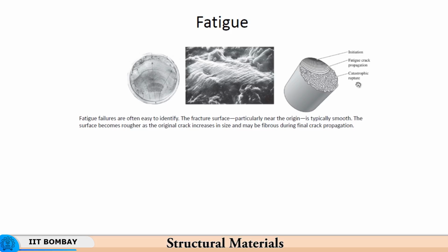Whereas here, the crack is propagating not at once, but it is arrested at various times, because you load the workpiece, the crack propagates, then you relax the load, the crack gets arrested, again it propagates, again it gets arrested. Since you have loading cycles, it is not monotonic loading, and the load levels in cyclic loading do not extend beyond the limit. So you have, let's say, cycles of 100 MPa. You reach 100 MPa and come down to 0.